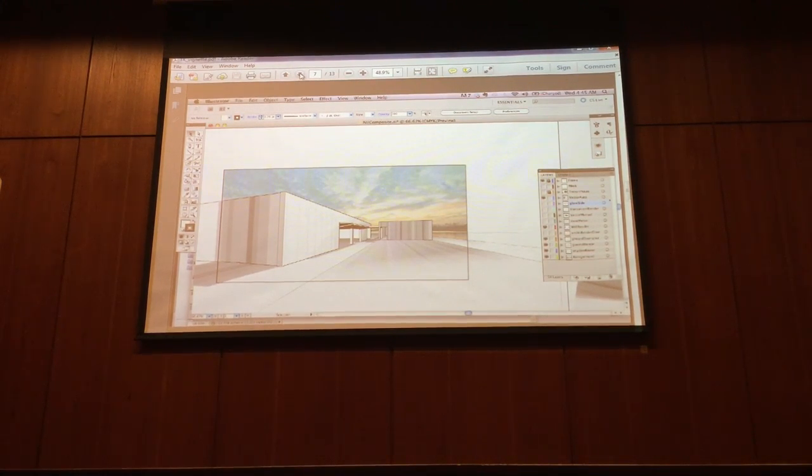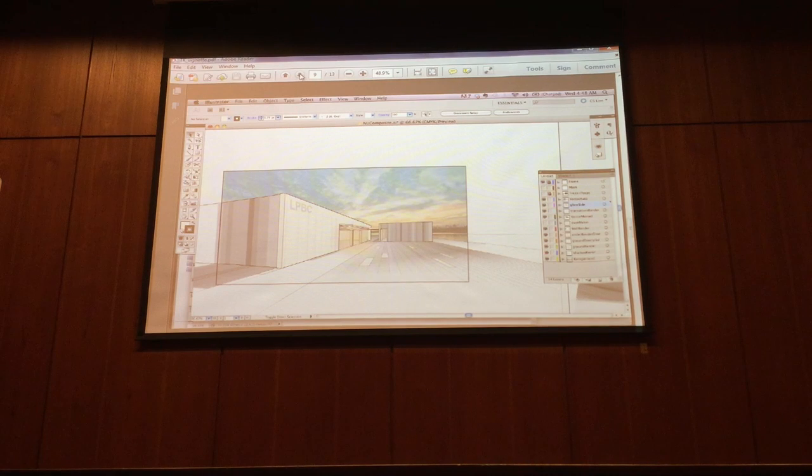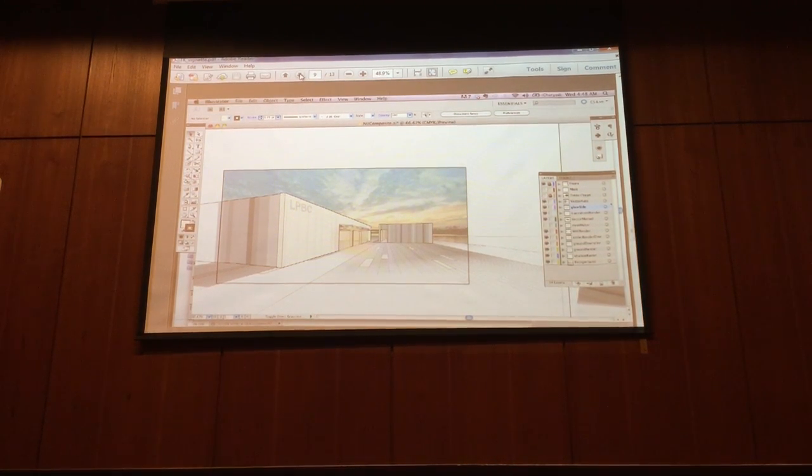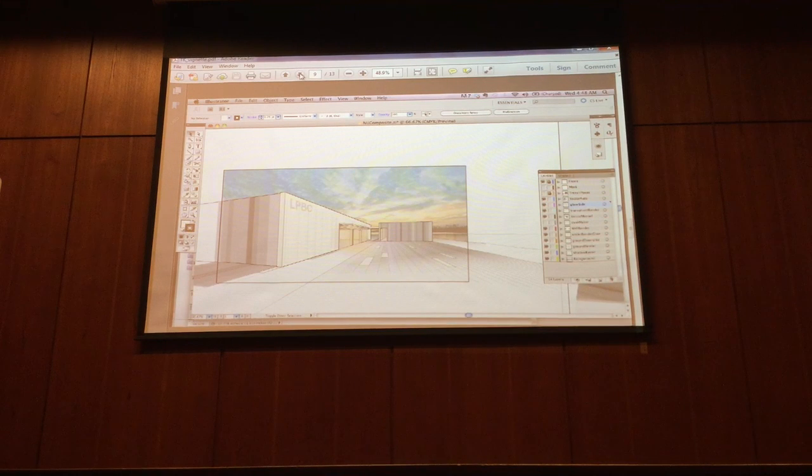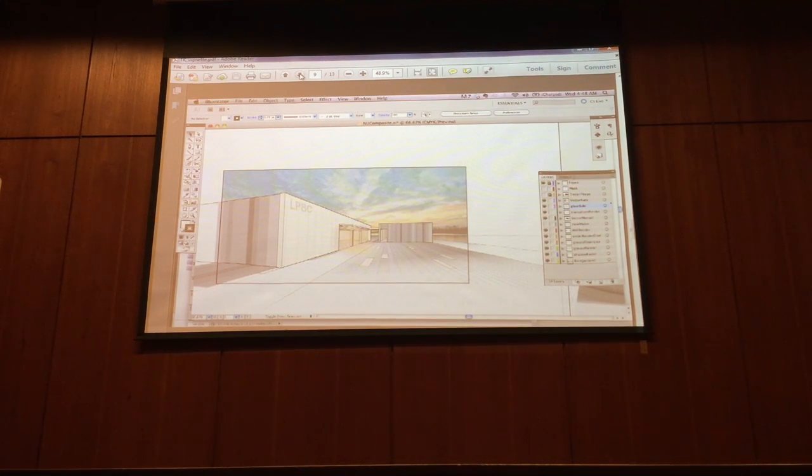And then some mask, bring some more line work in. If you save your views, you can go add more detail and get more line weights. If you export, if you layer everything properly, you can get different names of all the line weights that come into Illustrator. You can also use pen styles, tactical drawing, and they come with some edge. You can make your own pen styles in Rhino.